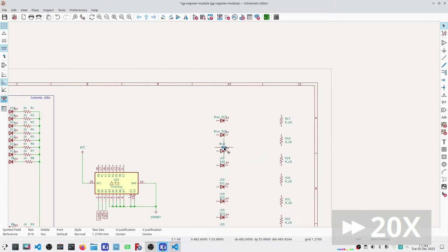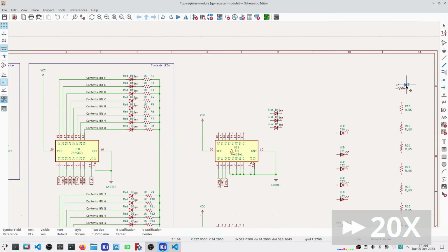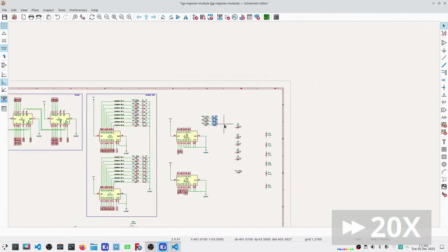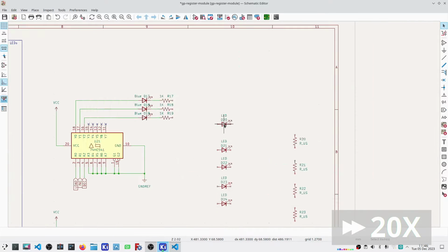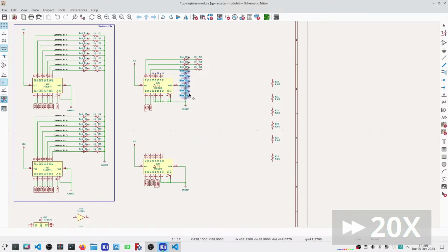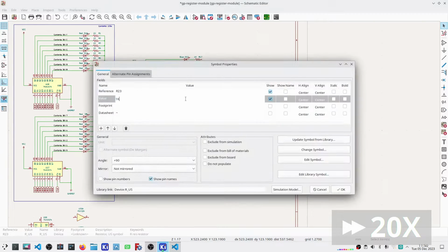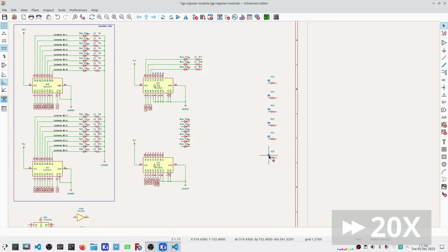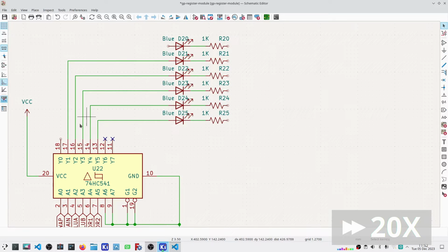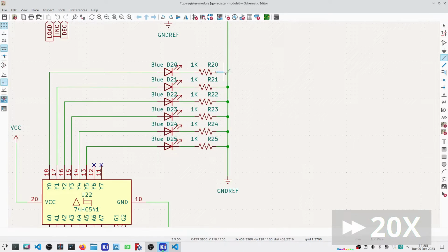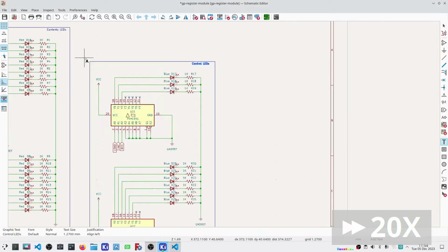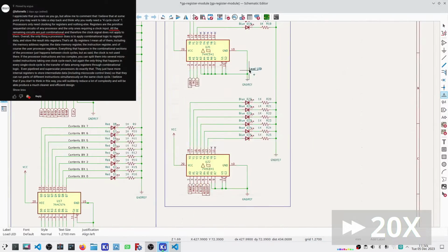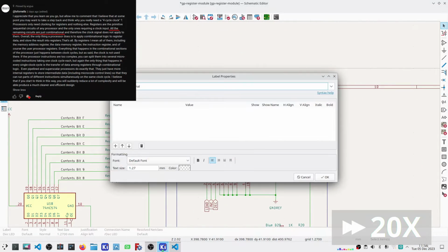That means that I now have to have a control signal that is on or enabled for the entire clock cycle, which is fine, but it forces me into changing that I am going to shape that signal at the module itself. If something was to cause that signal to have to change for whatever reason, that shape, then that will end up forcing a redesign of the actual module. Is that a big deal? I don't believe so, because other than the clock signal forcing a latch of all the registers, everything else is combinational. I keep coming back to that. So I don't think I'm going to have a problem with that.